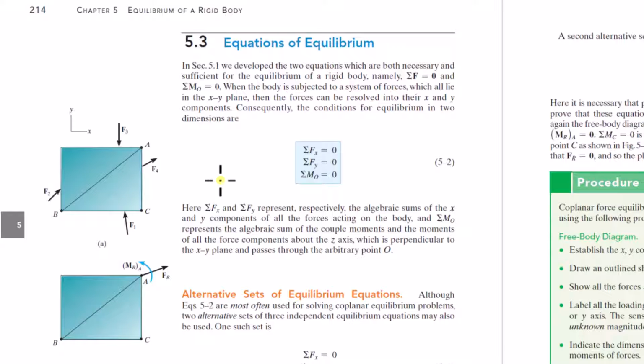Well, in that case, there is no moment. The forces have no net moment. Because you might say, well, why? You could pick a certain point in space and find the moment of the forces. Well, no. Remember this condition here, we could pick any point we want. So let's just pick that common point to make it easy. Well, there's no moment about that point. There you go.